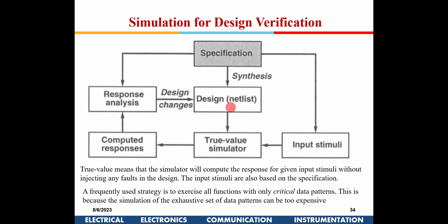Now in the next class, I'll talk about design verification. Testing is actually trying to find out if there is a fault or not in the circuit. In testing I am not really checking the logic verification aspect. Logic verification will be done in simulation for design verification. After fabrication, testing is essentially trying to find faults which might have occurred during fabrication. It is not trying to find out if a plus b is giving c or not. That will be done in design verification. In testing I am asking, has this OR gate been implemented properly?